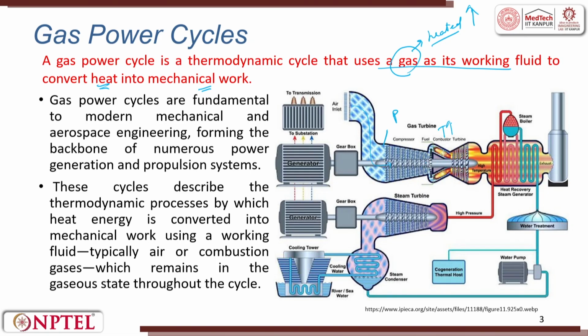Here the T increases, P increases. Here what happens? P decreases and T also decreases. By doing so, it turns the turbine blades. When it turns the turbine blades, the output is taken to a gearbox where they have a ratio of 1:5, 1:10 or something. So they accelerate or amplify. A gearbox is nothing but a mechanical amplifier, a multiplying or dividing agent. You can increase or decrease the speed, wherein you make a compromise on your torque. So then the gearbox is attached.